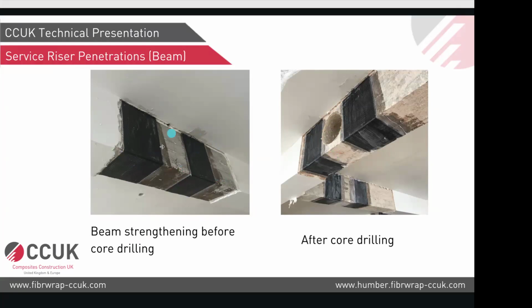Once the FRP was cured, then they core the opening. So as soon as you cut the rebar, the force will transfer to the FRP and there will be no localized concentration. From the architect's point of view, this was quite a neat solution because they're not putting additional steel underneath. They can plaster over it and it will be all concealed. So that's the reason that the architect also loved the solution.